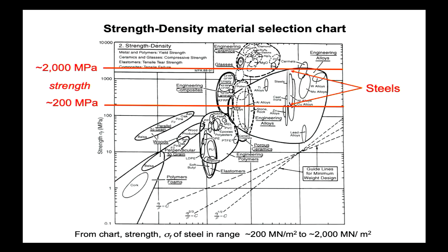But the point being, it's a pretty big range. You don't ever say steel, about 200 megapascals yield, because this little tool is telling you, nah, there's a whole family of steels. So you can go higher, but I can promise you, as you go for that highest strength steel, then with CES, go and have a look how much it costs. I'll promise you, it'll be a lot more than bog ordinary mild steel down the bottom.